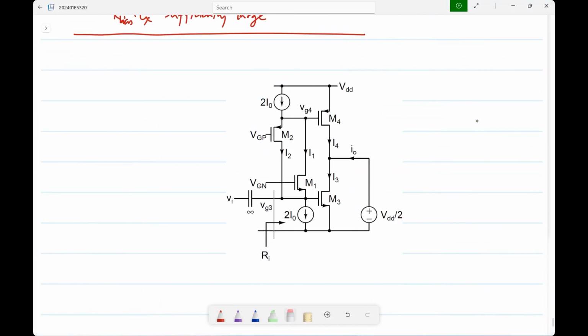So the thing is, it should still look like a common source amplifier. The input resistance should be infinite, because there are ways of fixing the bias current, but then completely ruining the signal picture. Okay, that's not what you want. You want it to behave like a common source amplifier. Now, you applied Vi. Again, I used AC coupling just for simplification in that problem. What was the, do you remember the signal swing that appeared here and there? No? Both are Vi, I think. You probably have found that both are Vi or something like that.